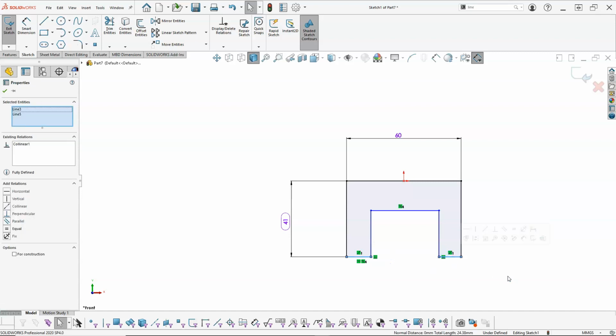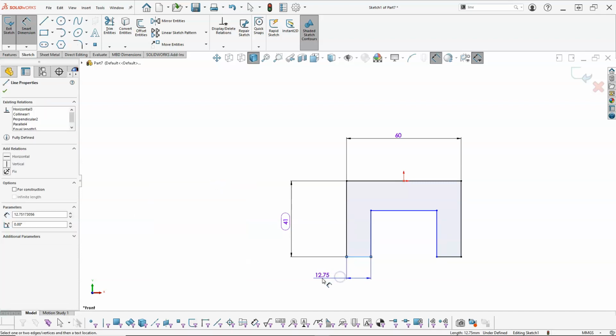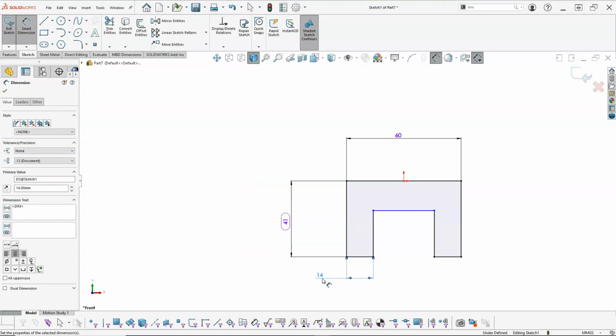So in this case, I haven't generated a center line. To create symmetry, I'm going to select, hold down the Control button, select the other line, and we're going to make those equal. All right, so once it has a dimension, we'll look for the smart dimensions here, 14 millimeters, and then the height was 21. The radiuses and chamfers, I'm not real worried about those right now.